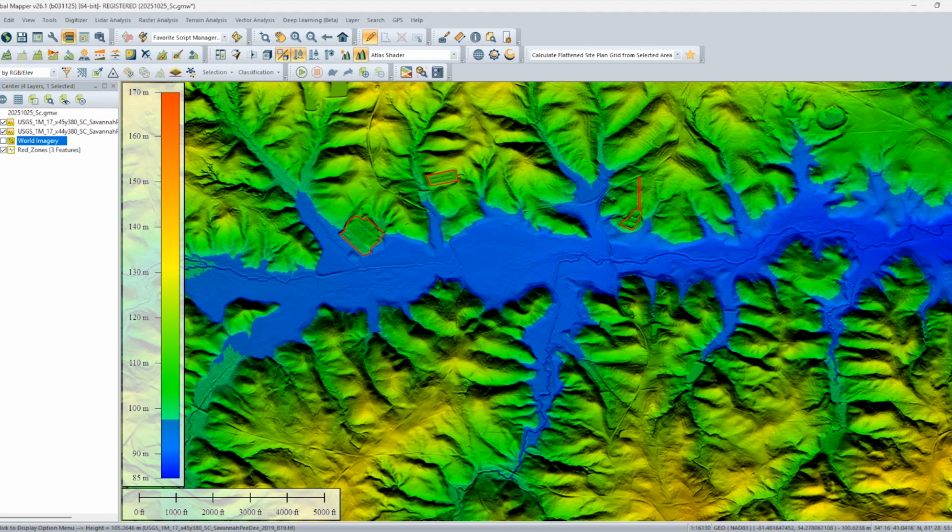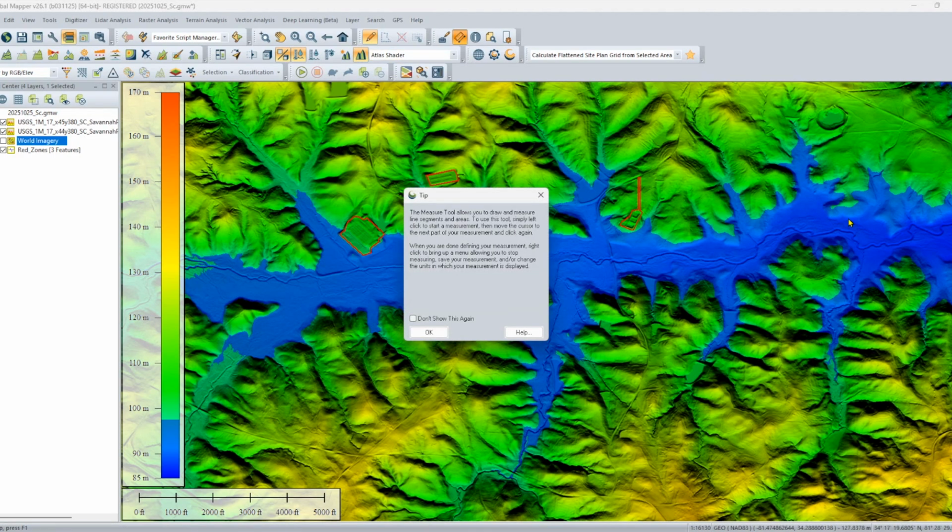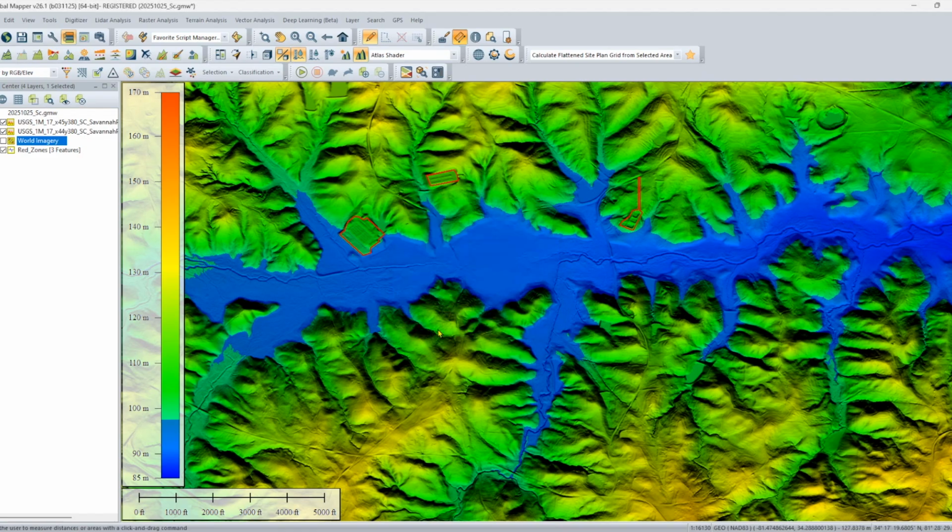If it starts creeping into the red zones, I know the elevation's too high. If it barely fills the valley, it's too low. For now, 320 feet is just the starting point. The idea is to find the maximum elevation first and find the optimum one later. We'll come back and fine-tune it once we decide exactly where to place the dam. That's when we'll balance storage volume, slope, and those flood limits we set earlier.